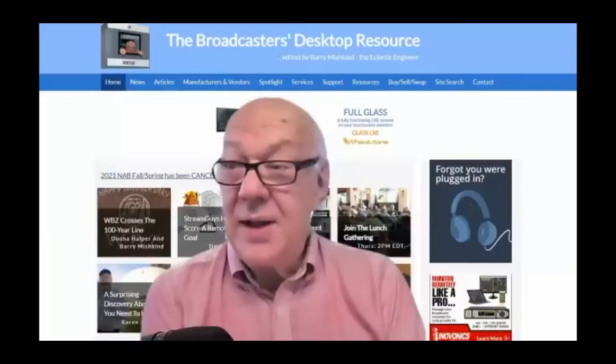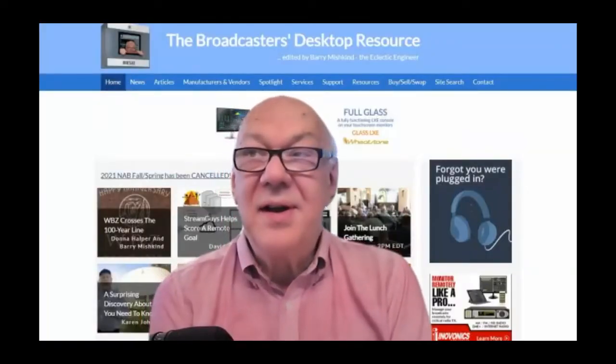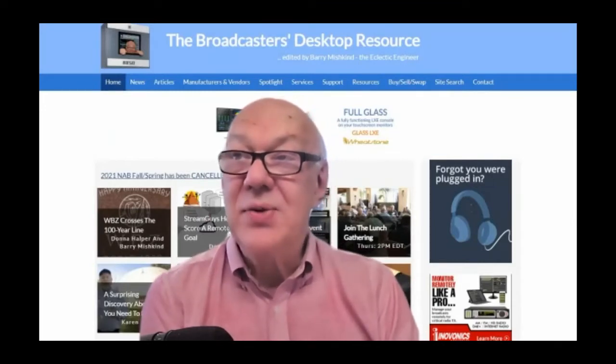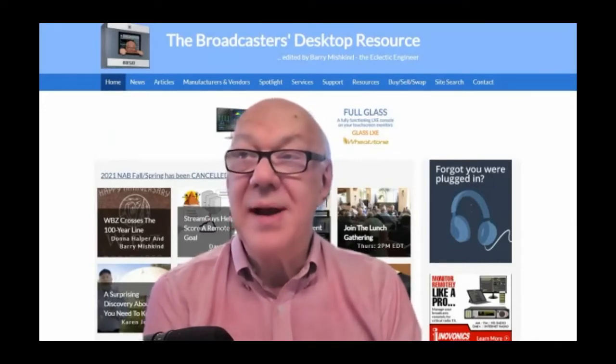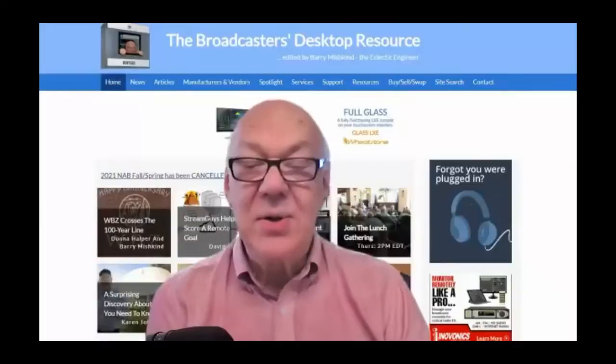If you're using it for security and a critical installation, at that point I might go more old school and use hardwired to a DVR, or whatever they record on these days. And also hide the camera a little bit in the eaves, or in a place where it isn't instantly recognizable by the bad guys. Yeah, and they're getting so small that it's a whole lot easier to do that. The PTZs still have a mechanical interface, so you're not going to get totally that small. But with regular cameras, you can put a fisheye lens in a peephole in a door, for example. Much easier now than it used to be.